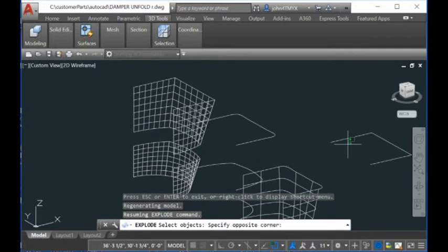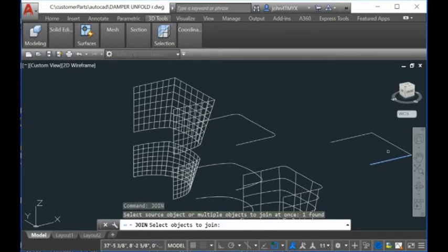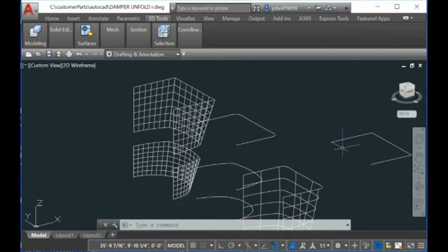This is the contour. Make a copy of that, and then you can get many such contours. What you can do then is join the curves. You join the three curves together, and this is actually a single composite curve. You cannot use a composite curve to loft a surface. If you use that composite curve to loft a surface, then it doesn't work.